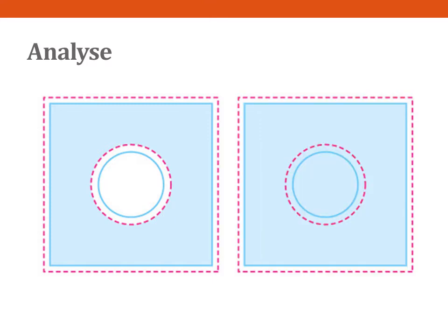Imagine that we have a similar metal sheet, but without a hole. Draw an imaginary circular line representing the circular hole in the situation. How does this imaginary circle change as the metal is heated? Did you guess? Yes, it will get bigger. Therefore, you can guess that the hole will get larger.